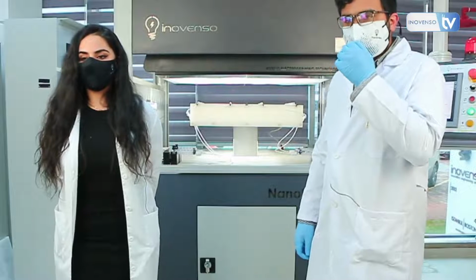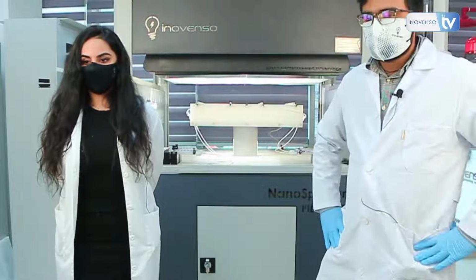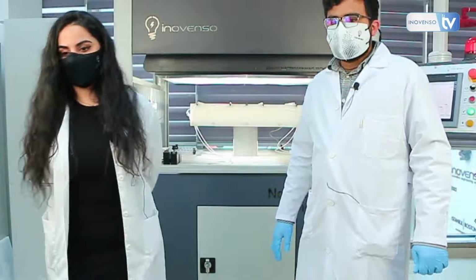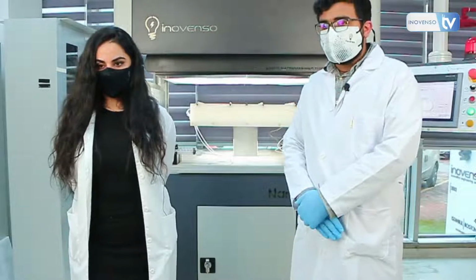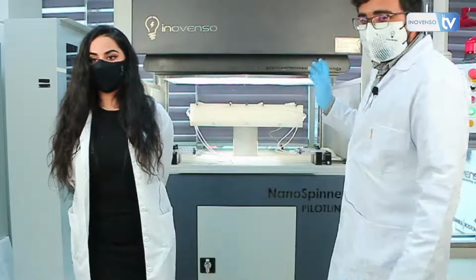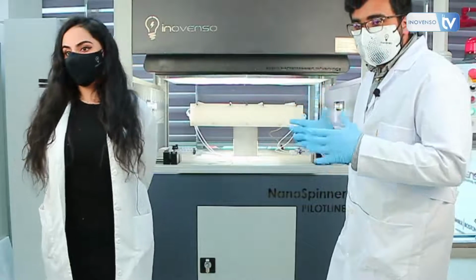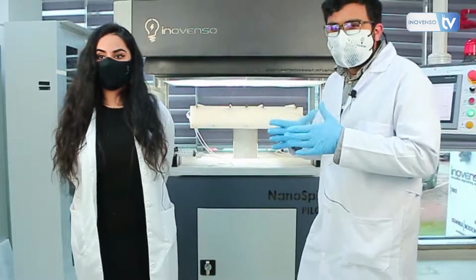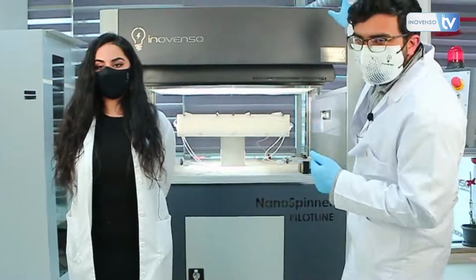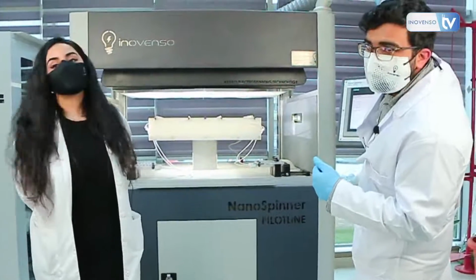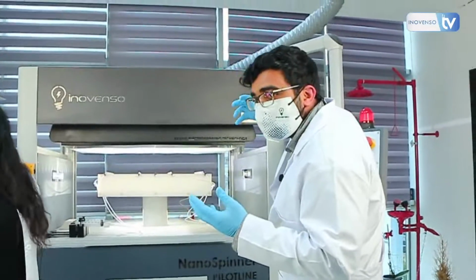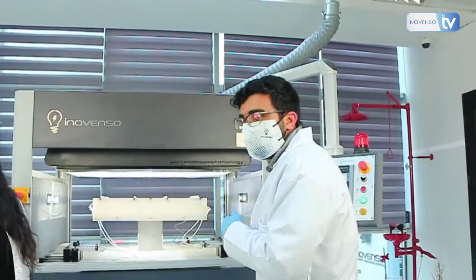So let's see if we have any more questions. So we have a second question here. How can I get rid of evaporated solvents? So yes, as I mentioned earlier, our machine has an exhaust fan. That fan is generally connected with a pleated hose or tube of about 105 millimeter in diameter. It's connected all the way, as you can see from the camera here, to your laboratory ventilation shaft or device. It evacuates the solvents from there, and it's supposed to be cleaned off that way.